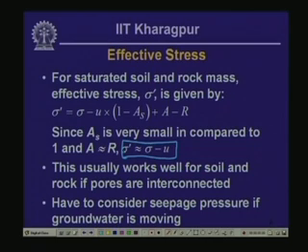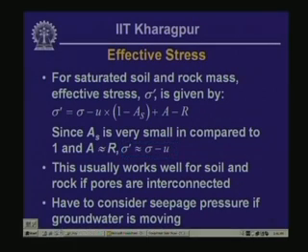So in simple cases what we are going to do is get the total stress, and simply subtract from the total stress the pore water pressure, and then we are going to get the effective stress.